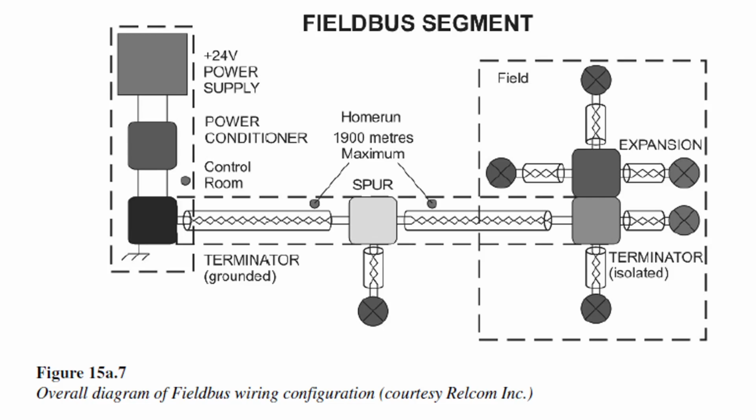What it does cost you more is cabling, right? So if you've got to run conduit from point A to point B and you're like, man, it's going to take me 4 hours to do that. Well, 4 hours at $50 an hour, that's $200 it's going to cost you to run it. I got to run $50 worth of cable. Okay, I got $250 now. Do I run a second cable now for an extra $50? Now I have $300 into this project. Or do I do it again and have $500 in the project in a year or two? Probably better off running that extra cable now if you can.